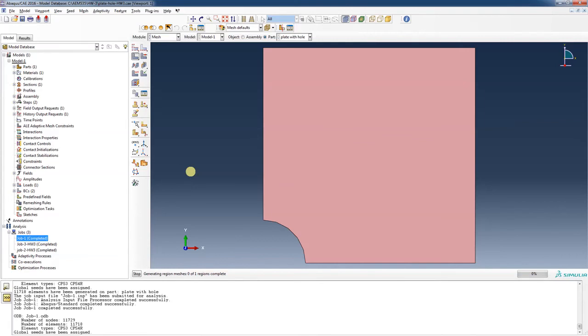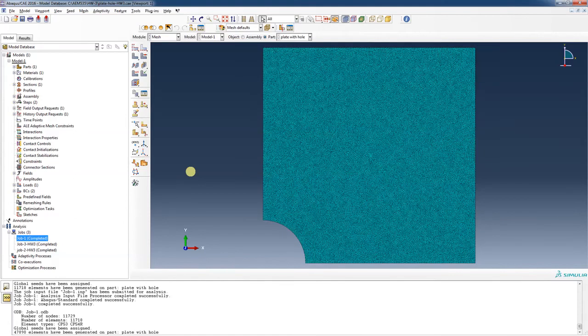Now our stress concentration factor chart said that we should get pretty close to 2.5. Now that stress concentration factor chart was derived from some analytical solutions done quite a few years back, well before computers were around. Some of the stress concentration factor charts that you might run across may have been determined experimentally as well, with something called photoelasticity. But here we're seeing what happens when we use this finite element analysis.